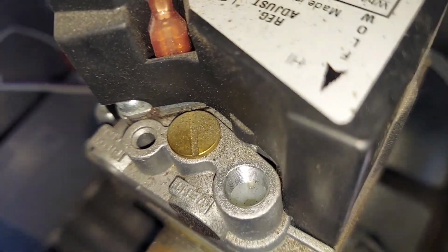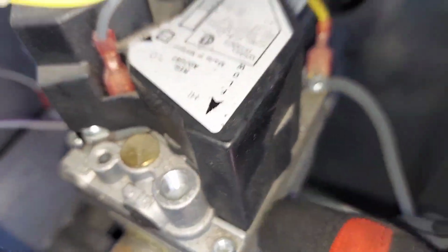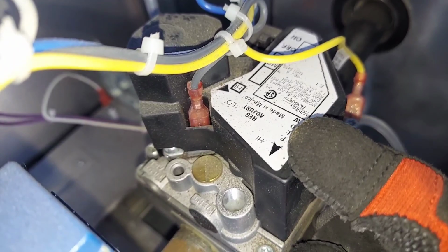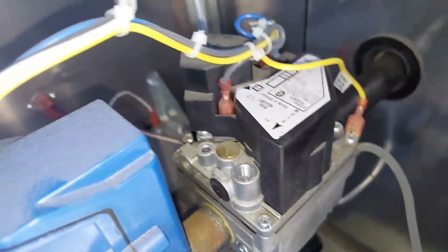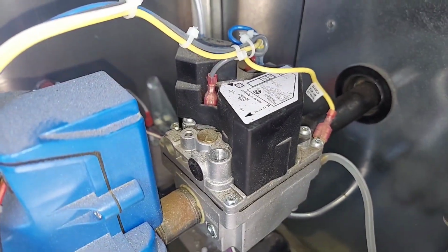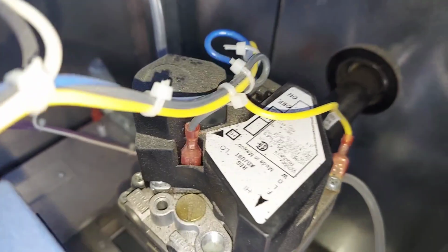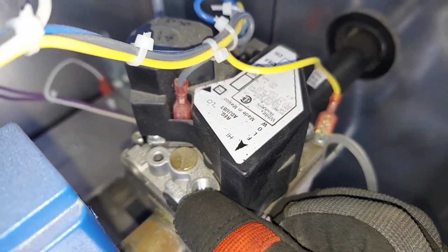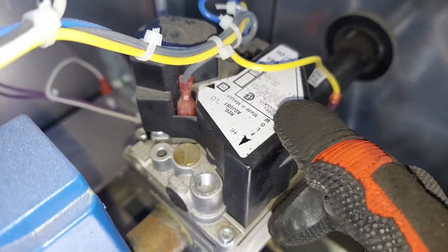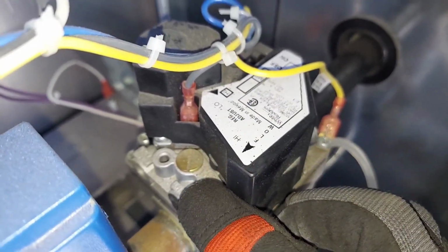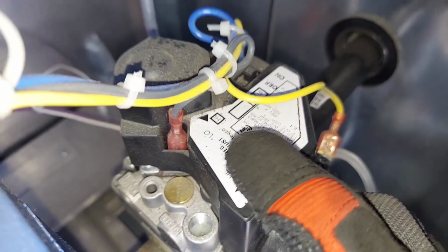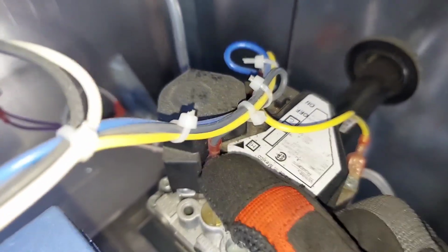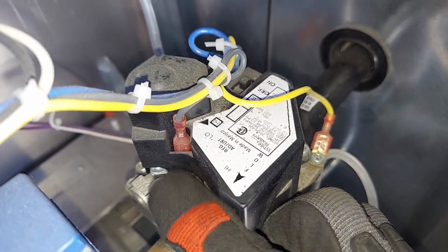So it's the same thing, but it's a smaller version. Now on the gas valve, you have the high fire adjustment. This is the high fire, because it's a 2-stage gas valve. You have high and low fire in this gas valve, right? So the 2-stage gas valve. You have the high, right here, the arrow. Naturally, no, this is the flow. But the high is this adjustment right here, the regulator adjustment, and over there you can see it says low. Obviously, right? Boom, that's one right there.